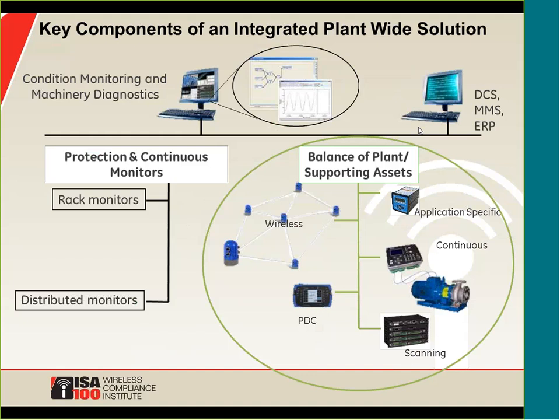Okay, what are some key components of an integrated plant-wide solution? Well, certainly on the continuous monitoring side, you have rack monitors and distributed monitors that, in addition to providing the monitoring data, also provide protection as appropriate to the more critical pieces of equipment.